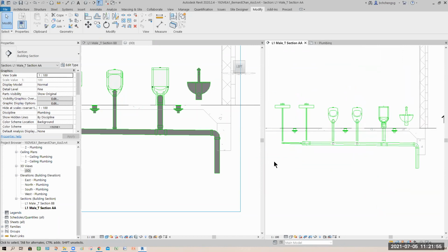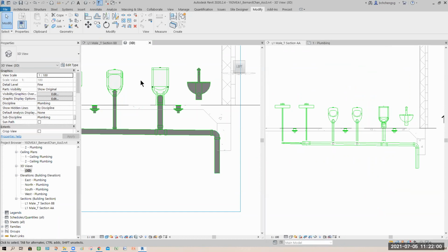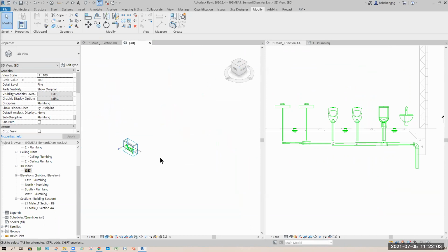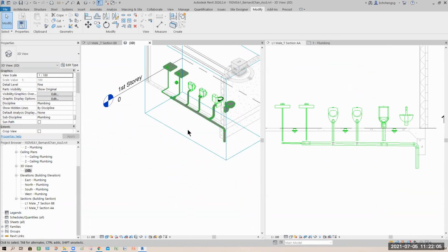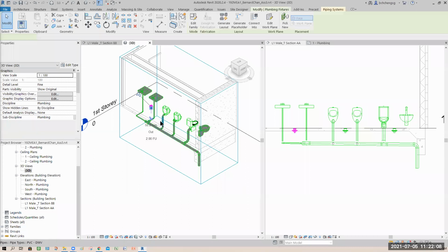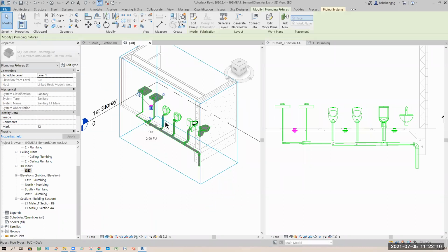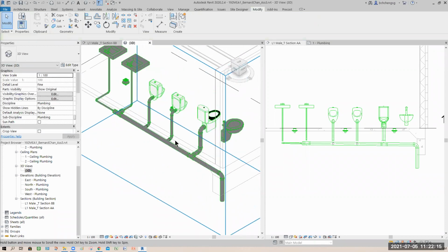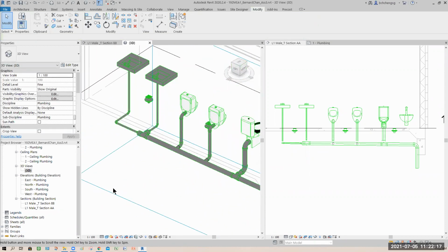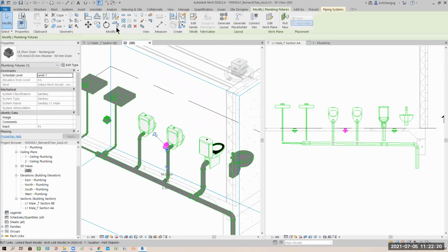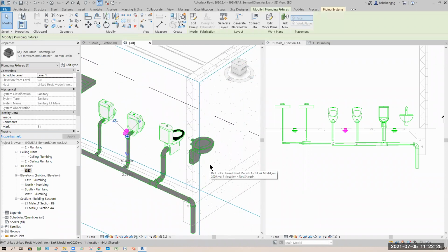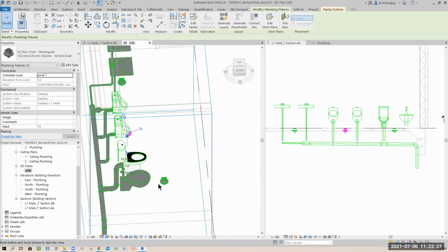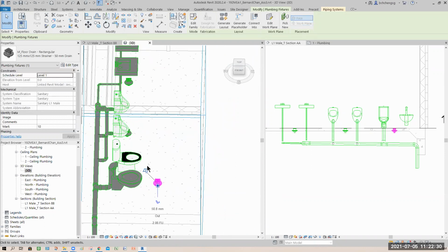Okay, now how to delete everything clean. Ideally, go to your 3D. Why? Pin all your components. Like this one I never pinned, right? Pin it, remember, because I know the rest we pinned. So when you need to delete, you don't need to worry that you are deleting your sanitary components away. This one temporarily I will pin because I don't want them to be selected.